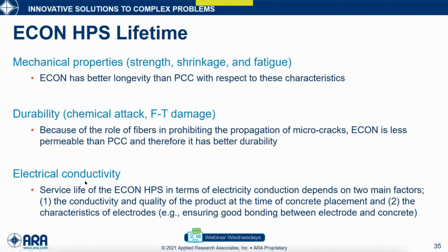In terms of heat generation, we focus more on the electrical conductivity, which is the reciprocal of electrical resistivity. When you design and build it, we try to achieve a good resistivity value, as I mentioned, below 1,000 ohm centimeter, to provide sufficient heat and allow electrical current to pass through the system.